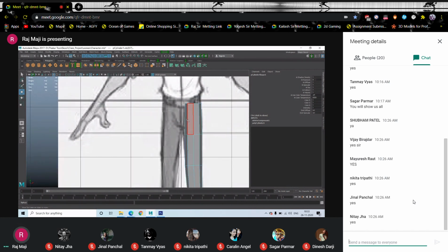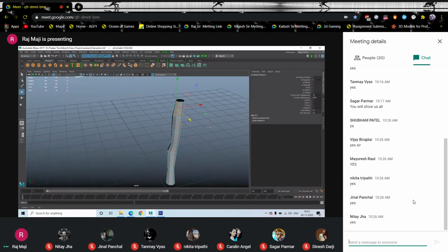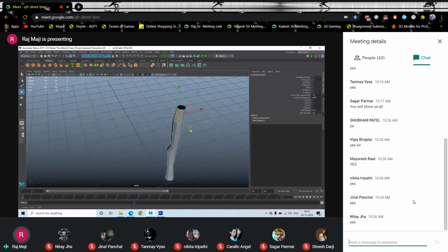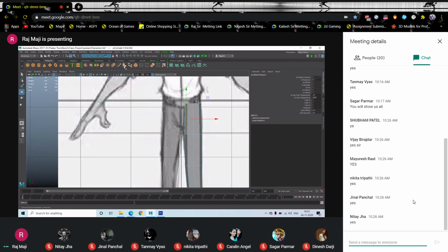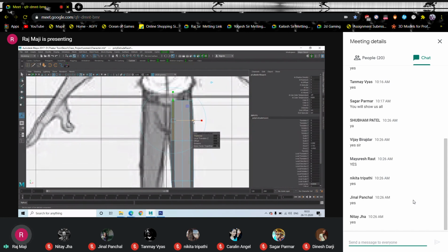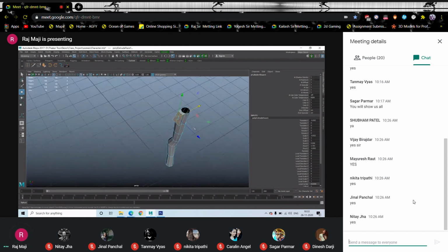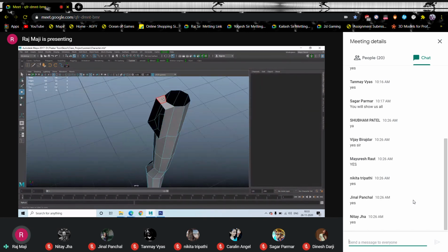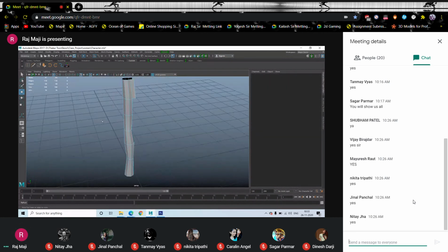Now go to this area and selecting these two faces. These two faces. Okay, and I'm extruding it. Extruding it in the global axis up to the center line. Scale it down, and then let's snap it to the center line. So I have snapped it to the center line. Now it is looking like this, and just delete. And these two also, just delete. That's looking like this.